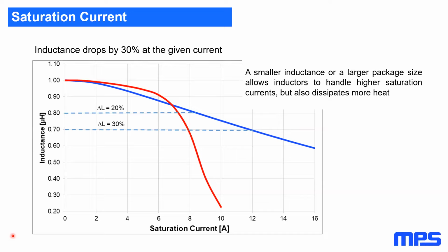And when we compare the shape or the appearance of the inductor, on the right side we see the MPS component, and on the left side, we see the component from the top vendors in the market. The one difference I noted immediately in this case is the start of winding. MPS is having the start of winding indication on the inductor, and the random vendor in the internet is not having this indication. So this start of winding really helps to increase the performance of your device, of your system. And we start to do this efficiency comparison with the MPS IC MPQ8883.